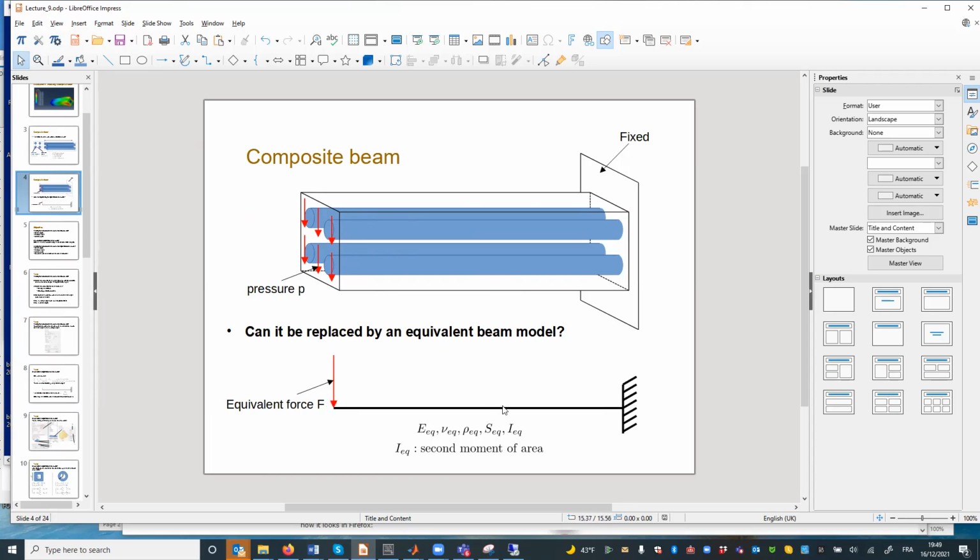For instance, in 2D, you cannot have the torsional modes. And also for the bending modes, each mode will be repeated in two directions. You will have a mode in the direction of your screen, and you will also have the same mode, but in the direction orthogonal to your screen by symmetry. But if you have a 2D model, the modes will not be repeated because it's 2D.